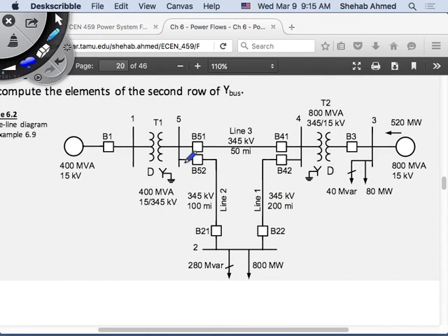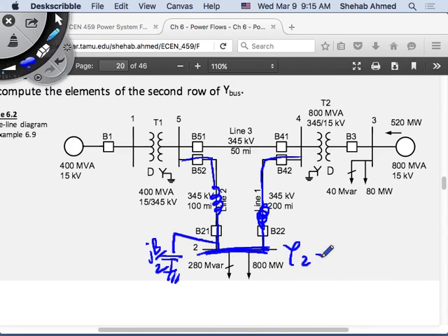Here I have this admittance, and I have a shunt branch here equal to jB over 2. They gave me B for line 2.5. So I have to consider this, that, and this as well, because Y22 is this plus this plus this.